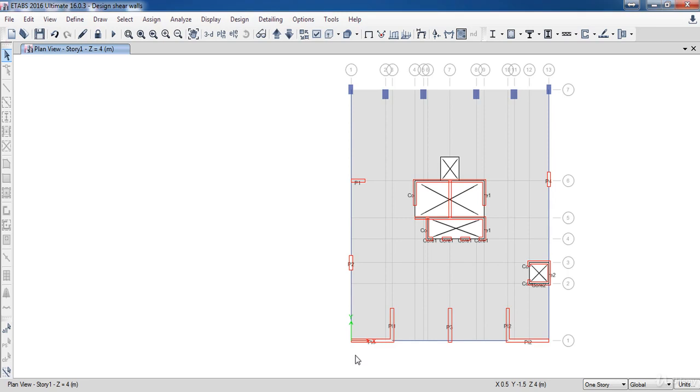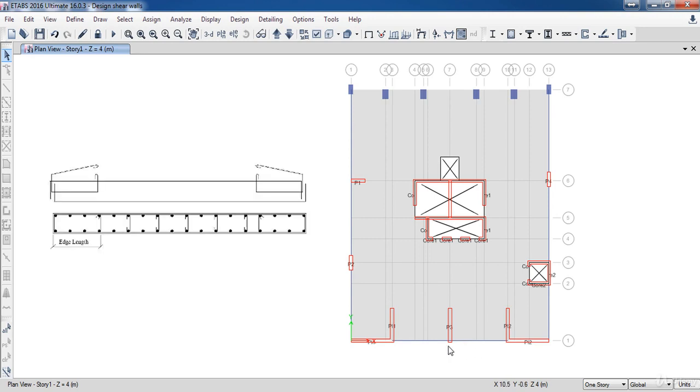In this lesson, we are going to learn how to design the shear wall using the general reinforcing method. This method allows us to add hidden columns in the shear walls, and ETABS takes their effect in design besides the uniformly distributed rebar.